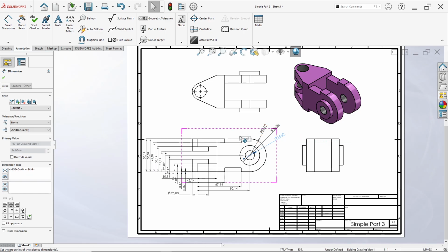For usefulness or benefit, the first is a faster workflow. It saves time when you want to quickly place many dimensions. Standard dimensions usually give the most important size references automatically, and it helps keep dimensions consistent, aligned, and neat. Good for drafts. You can use auto dimension to create a base set, then adjust or delete unnecessary ones.